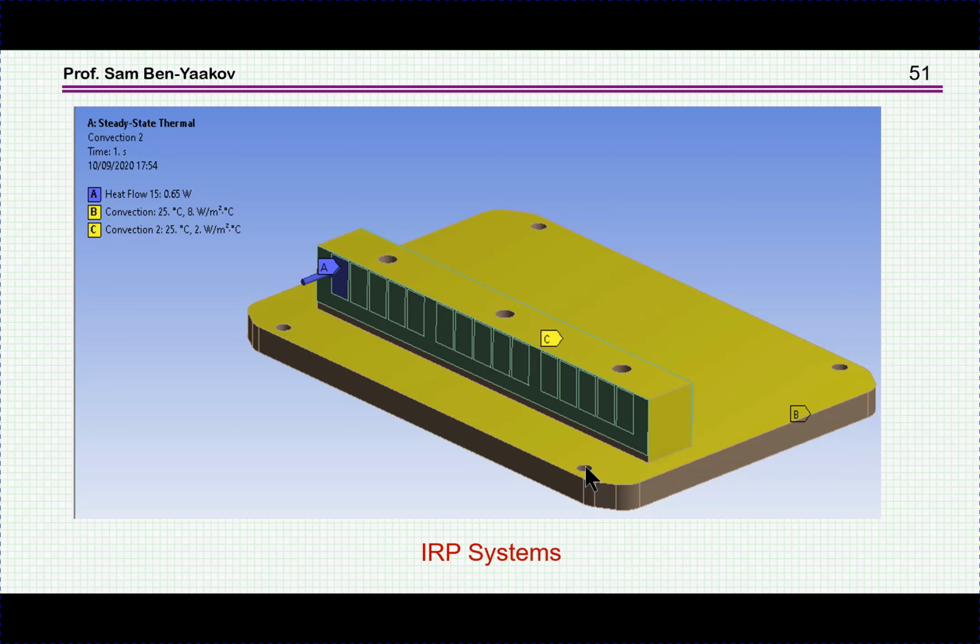So here is a way to get it in a more complex situation, which is very difficult to calculate by hand, if not impossible. This is done, or could be done, by finite element analysis, a thermal simulation, in which the program is breaking down the volume here. This is a 3D, three-dimension simulation, breaking it down into small cubicles, and then solving for each one of them the thermal equation, connecting them by the surface values.